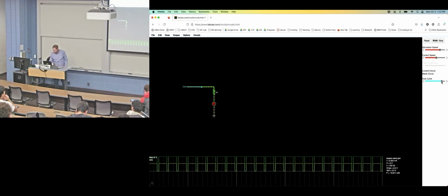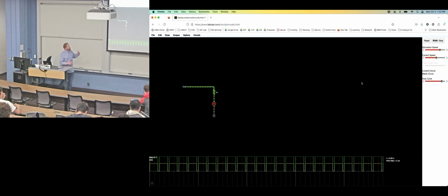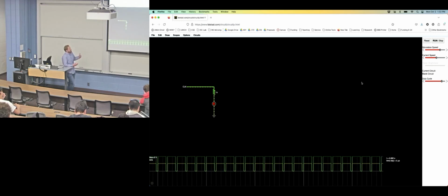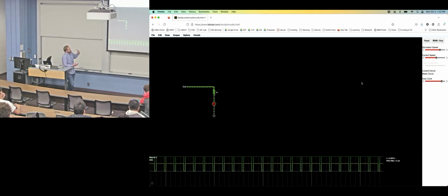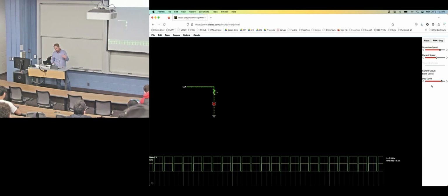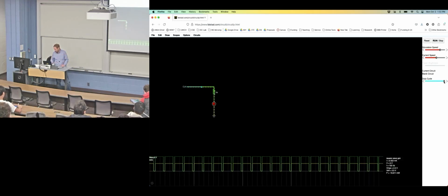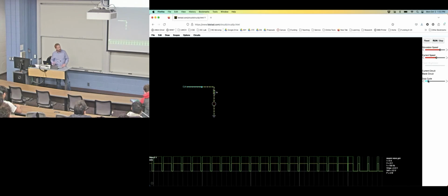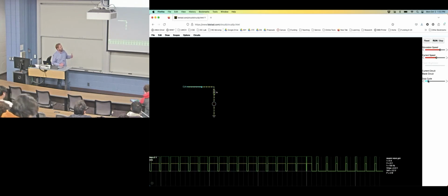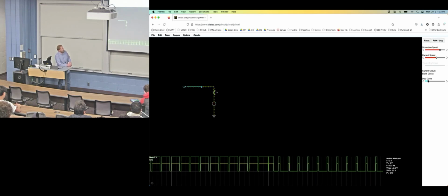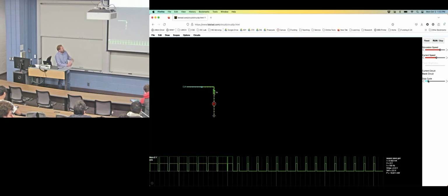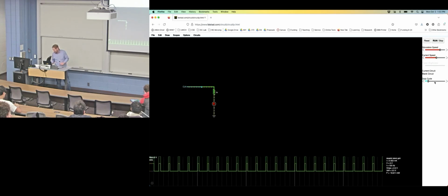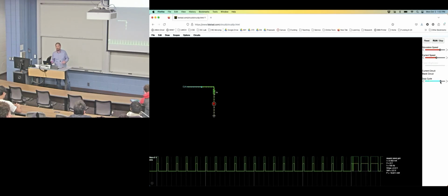And you can kind of see from this example, of course, it's being slowed down way more than a human would see, but you can control the effective brightness of an LED. This is how almost every LED on your electronics is controlled, through duty cycle. So in this case, it's mostly off, so your eye, assuming this is going relatively fast, over 100 hertz or so, will register this as dim, and then you would increase the duty cycle to have it be bright.